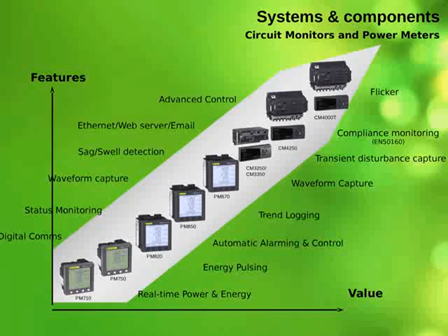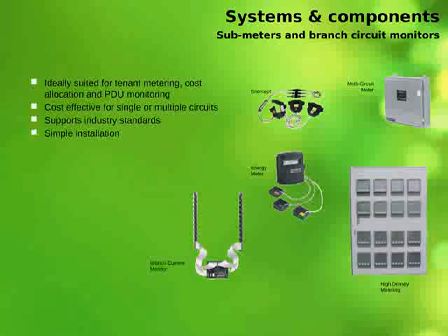Okay. Associated with the metering system and components, looking a little bit deeper into that, we talk about sub-meters and branch circuit monitors. Again, a different category of metering, and the reason why we talk about these categories is that they are very important to consider when talking about the equipment and or the loads that may need to be monitored beyond just the building or the main entrance.